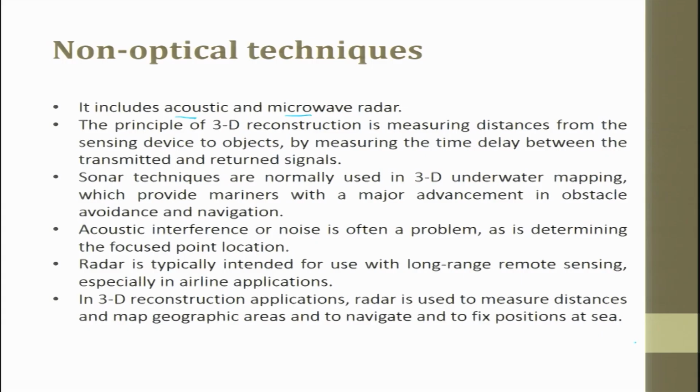So, acoustic sensors use frequencies in kilohertz. The wave is passed through the solid object, or the distance is measured through acoustic or microwave radars. The principle of 3D reconstruction is measuring distance from the sensing device to the object by measuring the time delay between the transmitted and the return signal. So, this is the time of flight technique, and then they try to figure out the delay in time. From there they find the distance, and from that distance XYZ coordinates can be obtained.